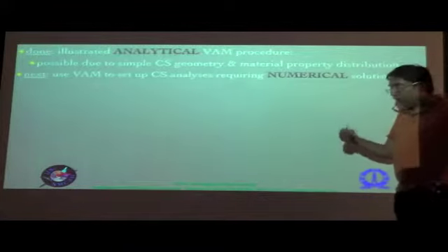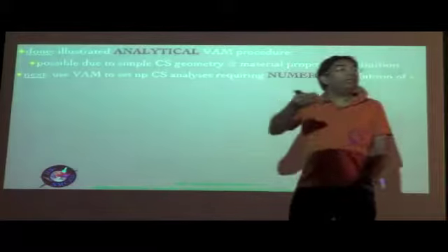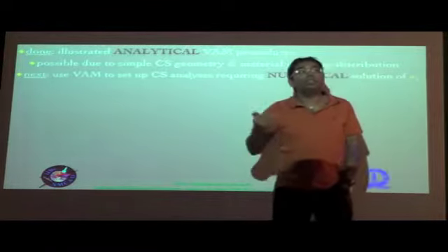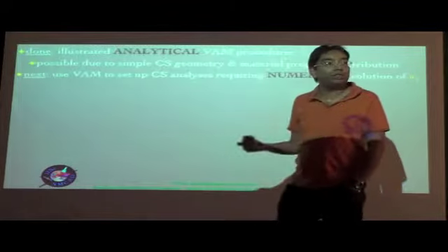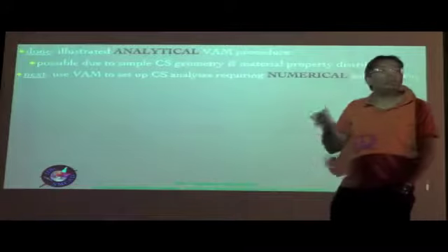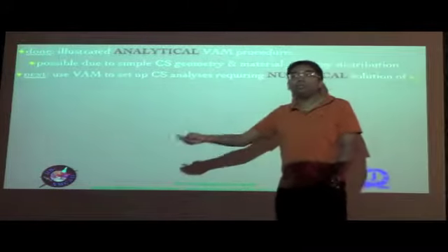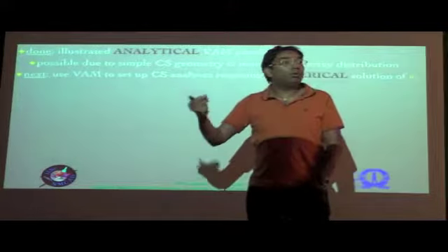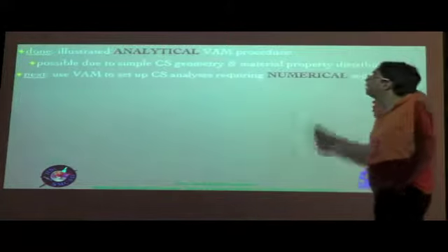If you remember, even in the previous problem, the Euler-Lagrange equations turned out to be nothing but the governing differential equations for W, the partial differential equations that you had for W, and you then determined the solution, which is nothing but the solution for W explicitly in terms of x2 and x3 and implicitly in terms of x1 through gamma 11 bar and the kappa bars, right?